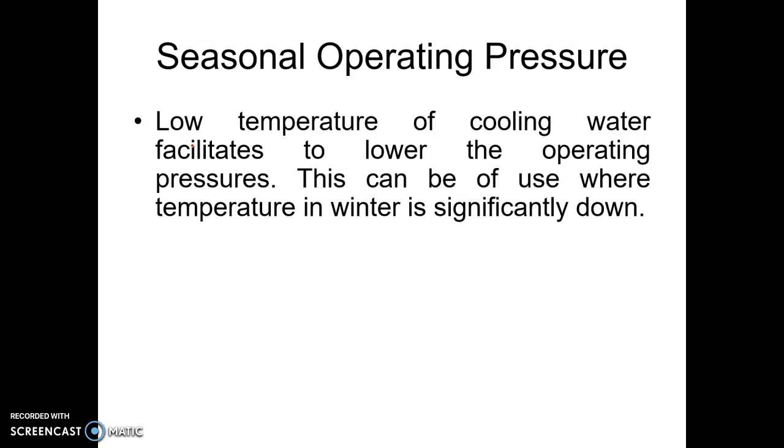Now, condenser temperature decrease means what? I have to supply a utility at a lower temperature. Now, say for example, if you are at a place where there is a huge temperature difference, in that case, the temperature of the cooling water will also change. Naturally, not as much as the other outside conditions, but cooling water temperature can also show you some degree of freedom.